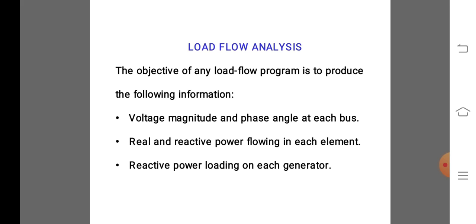When a prime mover drives an alternator supplying electrical power at a given frequency, a governor must be used to hold the prime mover at a speed that will yield this frequency. An unloaded diesel engine will fly to pieces unless it is under governor control.